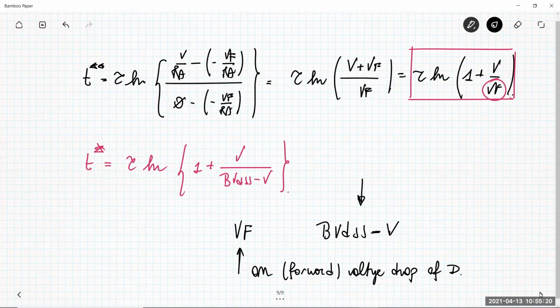As I said before, in an example, if V is 100 volt, the breakdown voltage can be 150, just to be sure to not reach this characteristic. Or if you want to reduce the energy involved in the breakdown region, BVDSS is much larger than V.